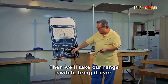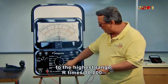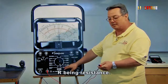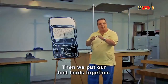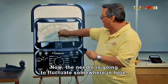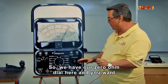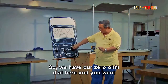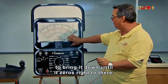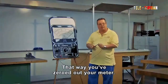Then we'll take our range switch, bring it over to the highest range, R times 10,000, R being resistance, and then we'd put our test leads together. Now the needle is going to fluctuate somewhere in here. What we want to do is zero this out. So we have our 0 ohm dial here, and you want to bring it down until it zeroes right to there. And that way you've zeroed out your meter.